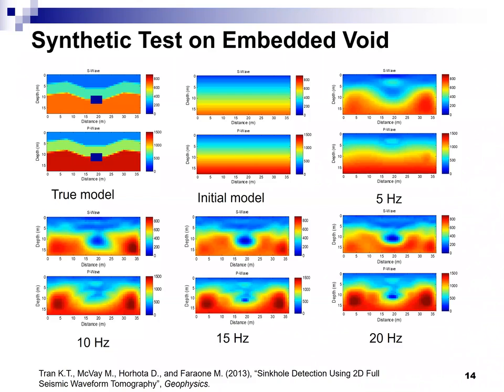Where does the initial model come from? We can estimate it from the dispersion curve. Is that from very low frequency? Could you put 1 Hertz where you have the initial model? No, it's the surface wave dispersion curve, obtained by just taking a 2D FFT of your waveform along the multi-channel array and looking at the dispersion curve. I will explain more for the real data. Right now we just accept it.